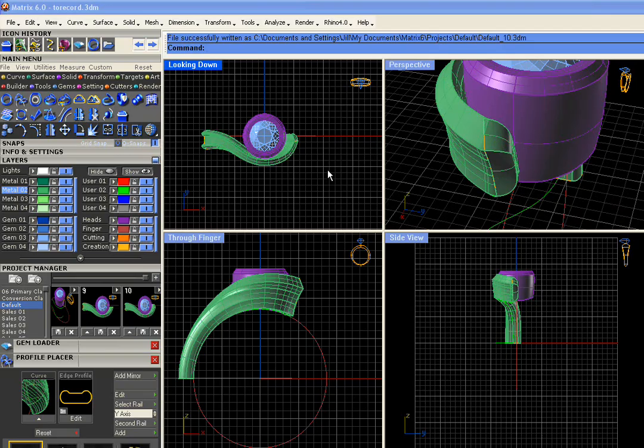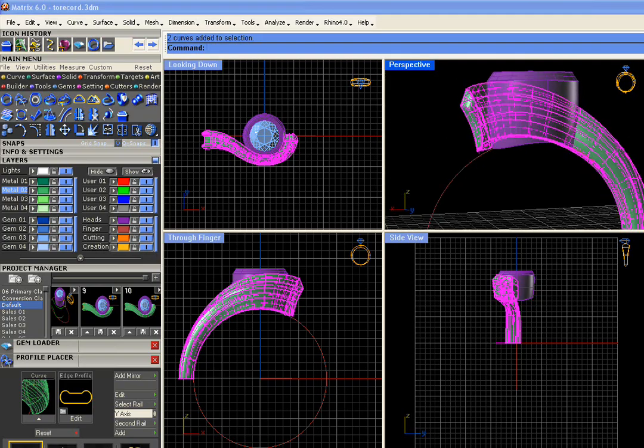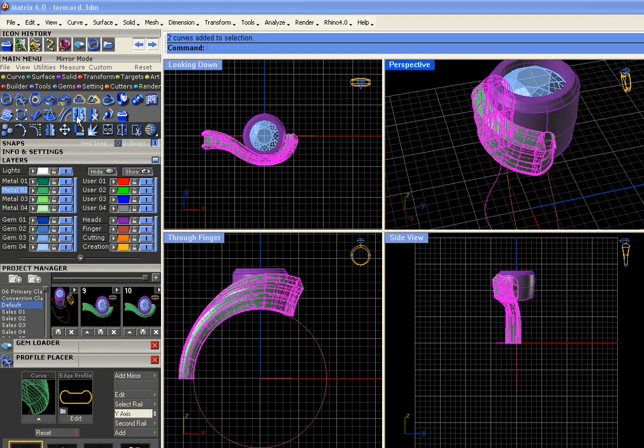And the only parts we need to rotate are the surfaces. Actually, for good measure, we can grab the surfaces and the curves. Just right-click on the color of the surfaces. That includes the end cap. And right-click on the color of the curves. Those are yellow. And we'll also grab the green curves, just so we know we've got everything together. Press the Rotate command, and make sure the copy option is turned on.